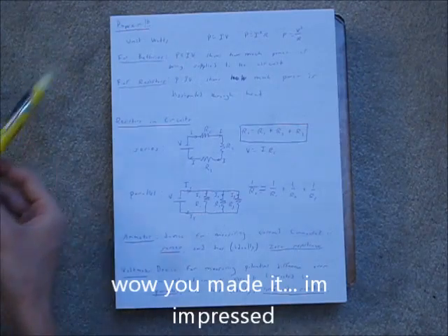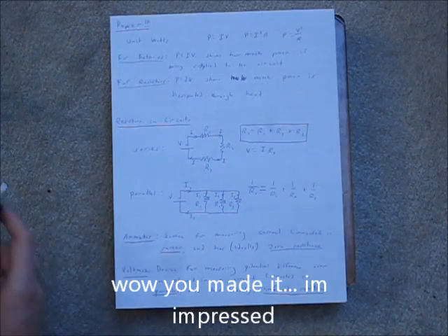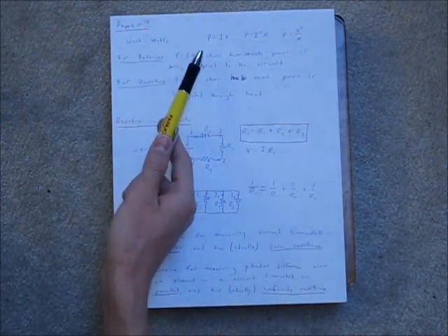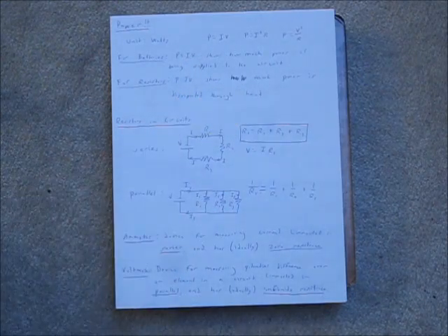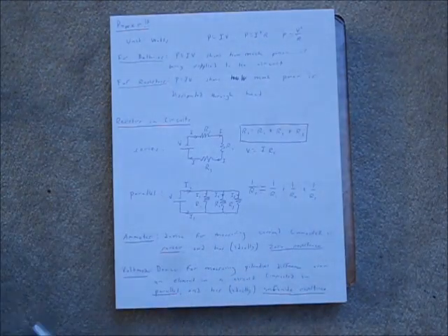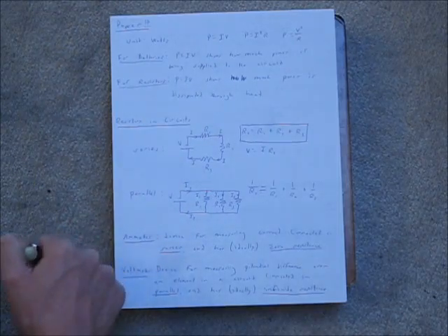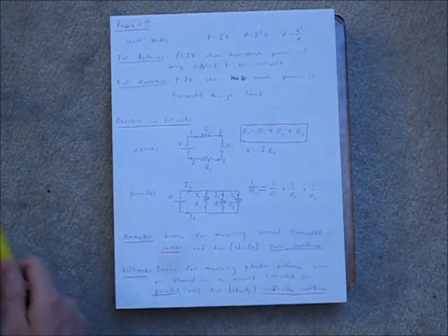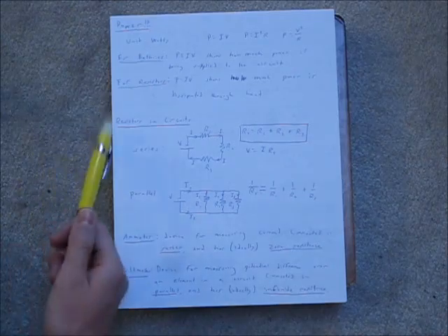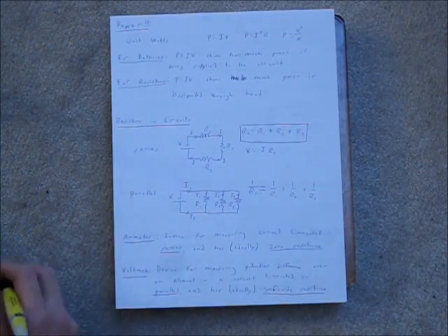So now we have power in circuits. It's measured in watts, and the equation we commonly use is P equals IV. Using Ohm's law, we can quickly derive these two other equations. If a problem is related to power of batteries, it is talking about the power supplied to the circuit by the battery. If it's talking about resistors, it's talking about the power dissipated by that resistor as heat.